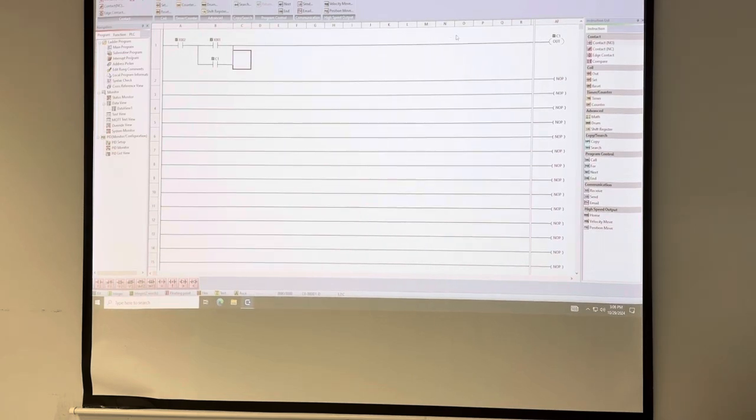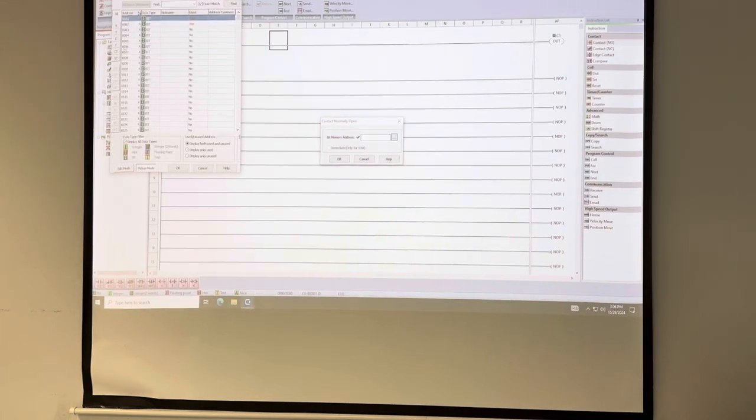It's a binary. When C1 becomes active, or 1, this C1 will be logic 1, holding this connection from the left to the right. And don't forget X002 is using negative logic, which means that it's open here, but at the hardware level it's closed. And right here, I will simulate. Look at this. I will use C2.